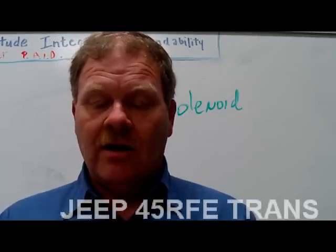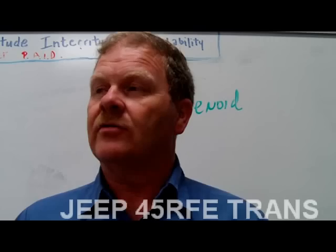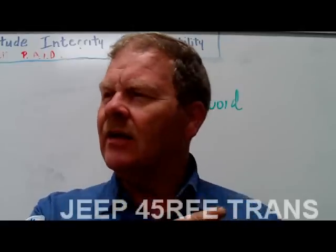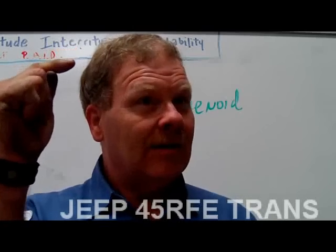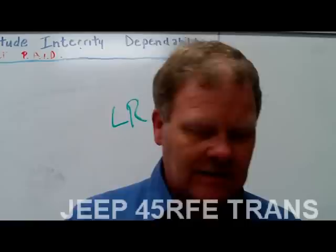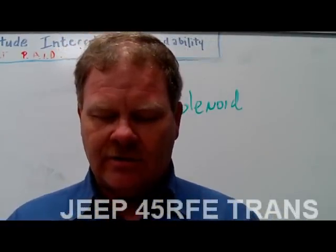And it monitors, listen to this, mainline pressure through the pressure sensor, and adjusts the pressure with the pressure control solenoid. I will tell you, and I've got a video here somewhere that I may have shown y'all, where I rode down the road with Michelle Taylor in her Jeep, and the target pressure for her line was different. Remember that? That's what we're talking about here. It was exactly that same transmission. All right, it monitors mainline pressure and controls it with a pressure control solenoid.